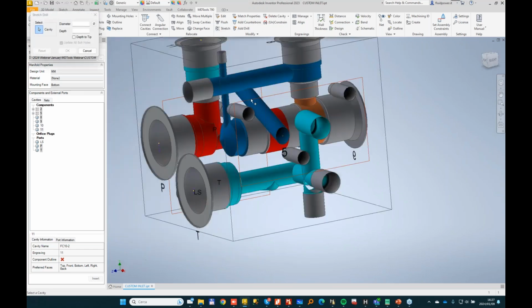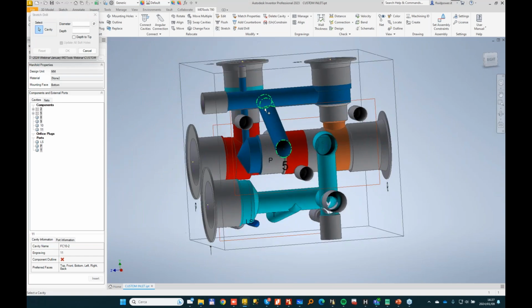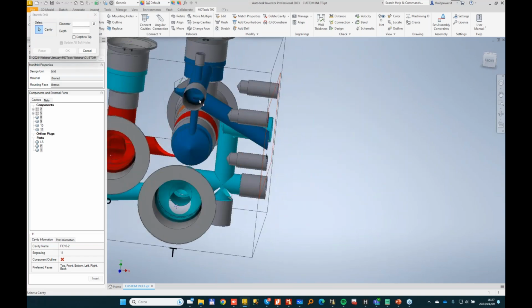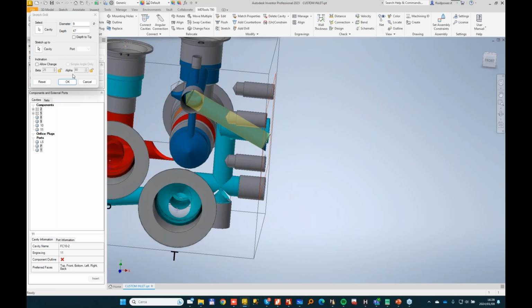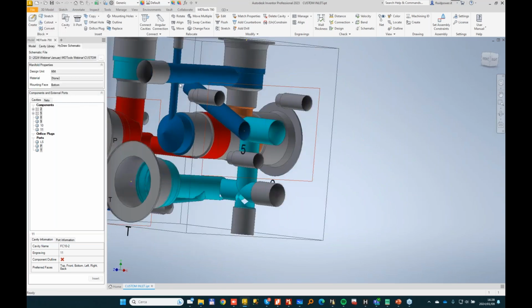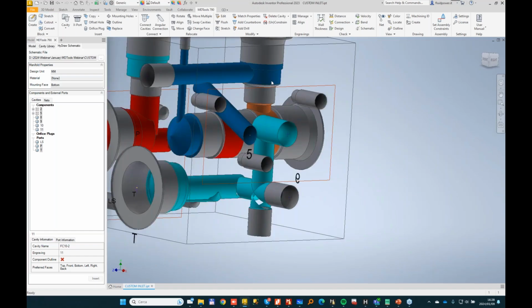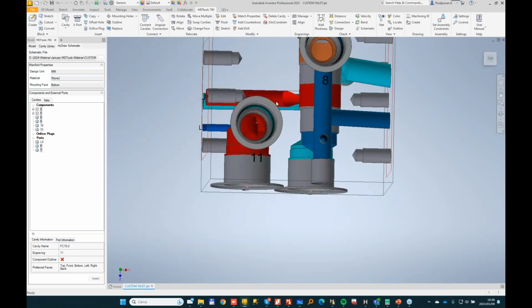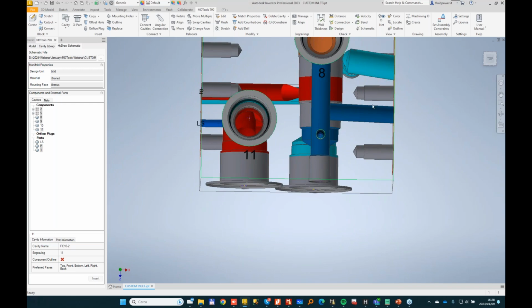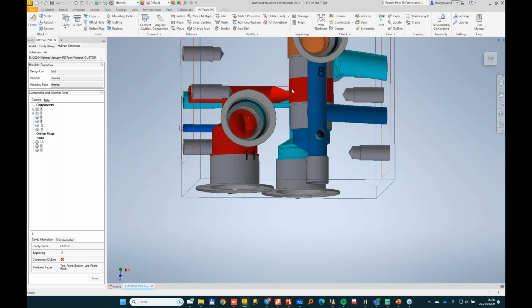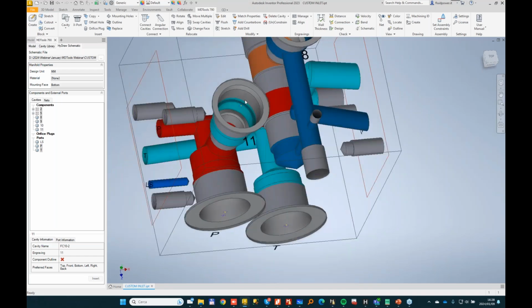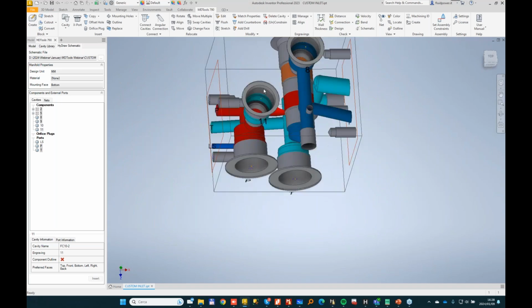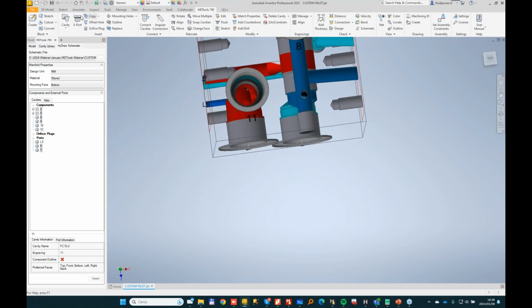Now, the choice to make this inclined drill may not be that great, but let's try. We'll probably need another plug, but let's first find a solution. Designing a manifold is always a hit and try. You find a solution, then you change idea because you find a different path for the design, for other complexity in the circuit.